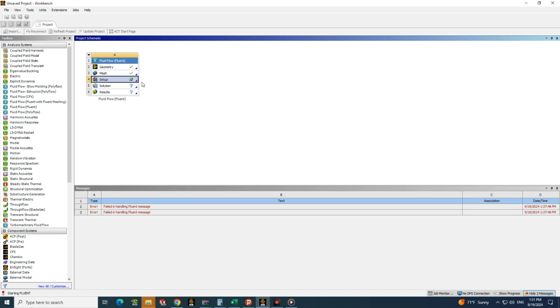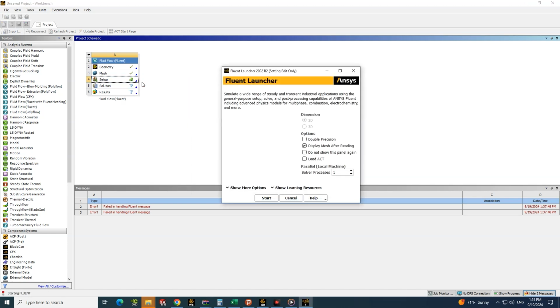Once again, we have to wait until it is loaded. You will see this table like this. We always click on double precision to have better answers, and do not increase more than 2. 2 is okay, because if you increase this one so much, it will ruin your case, your system, your PC. So never ever put more than 2 on this table and click on start.